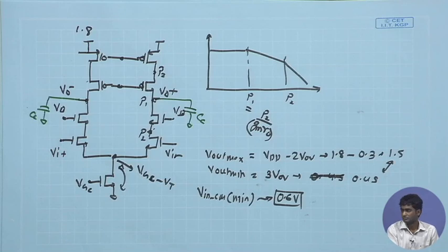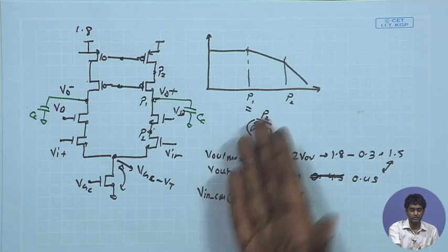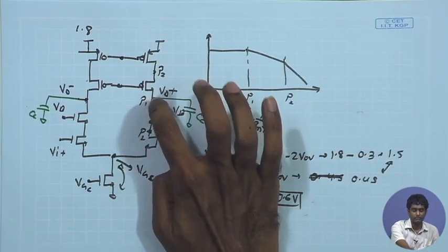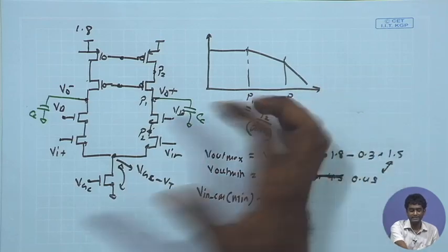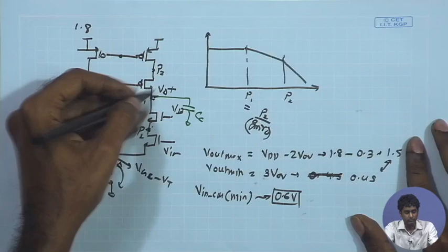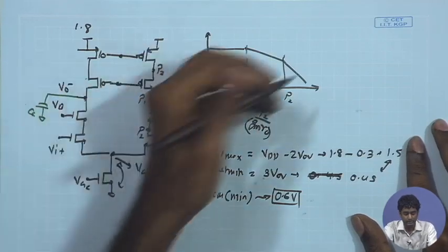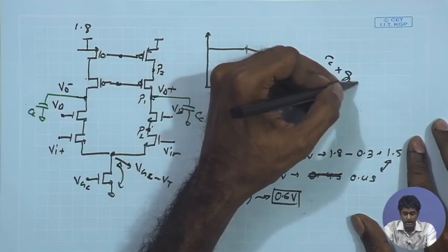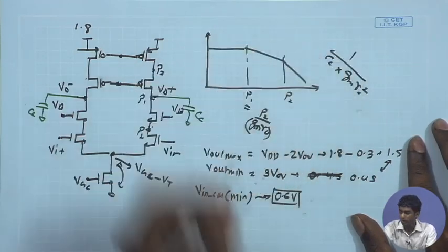So, what about bandwidth? If I look at the overall response, you are having the total bandwidth after compensation, even if you add CC, the total bandwidth is given by gm ro square. So, if I look at the overall C value, what is that? CC times the gm ro square, this is the pole overall.